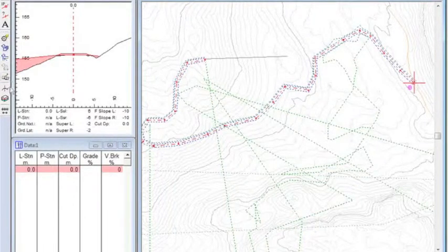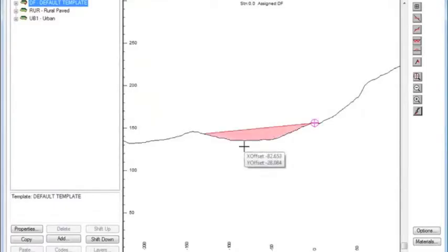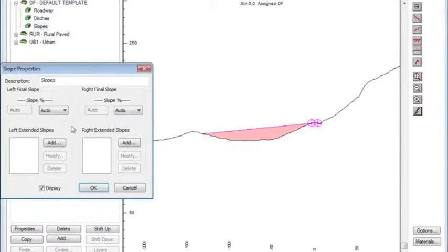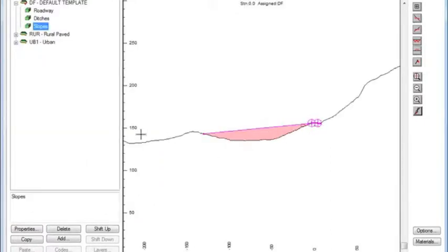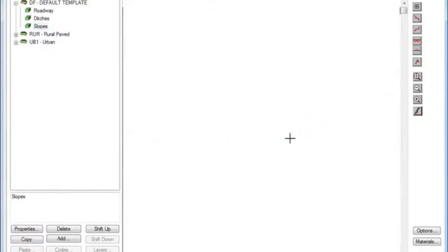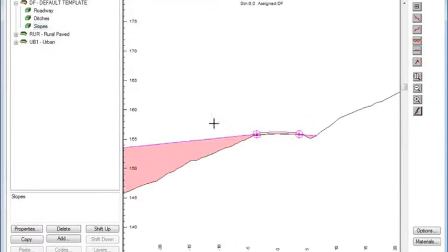First of all, what template are we using? Now I have my template table set up to have the default template look like a forest road, but one of the interesting things about this is it's using automatic fill slope for cut and fill on the outside. So my fill slope looks like garbage until I give it a reasonable material type. So let's do that.